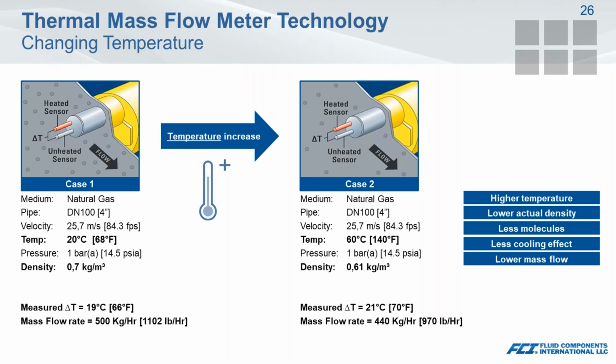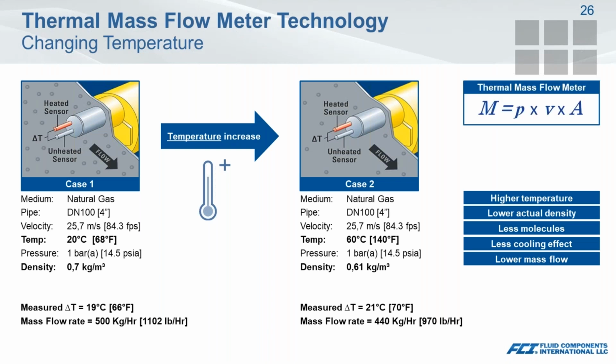So without taking into account these changes in process conditions, you're really not going to get the full understanding and the full measurement of the calorific value of your natural gas as you're trying to balance your readings. And again, this is supported through our simplified equation, where that change in temperature is going to affect our density. So all of this is accounted for without any additional instrumentation.